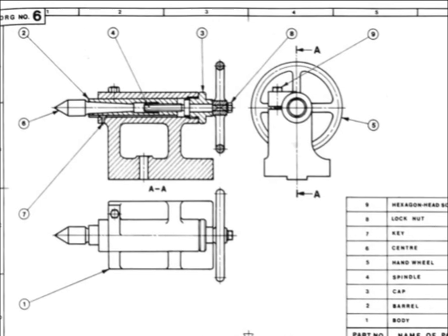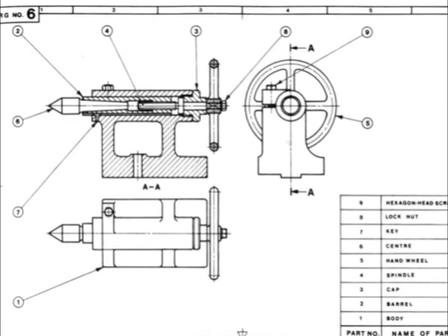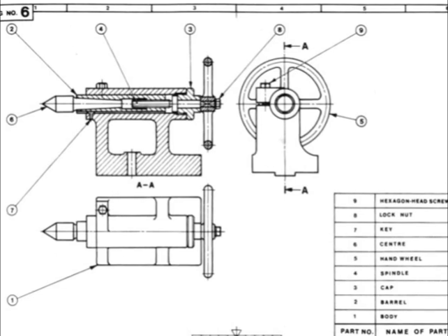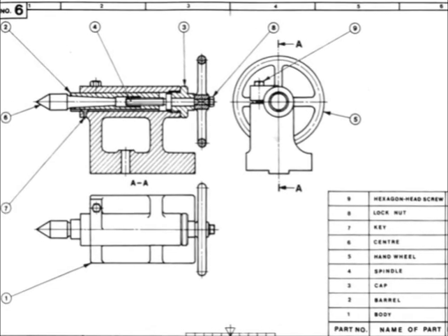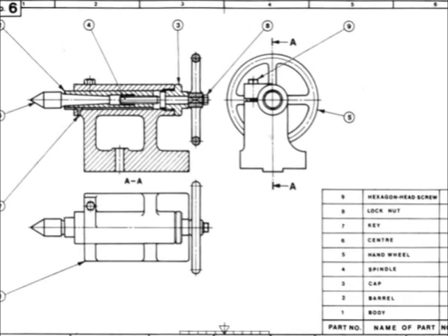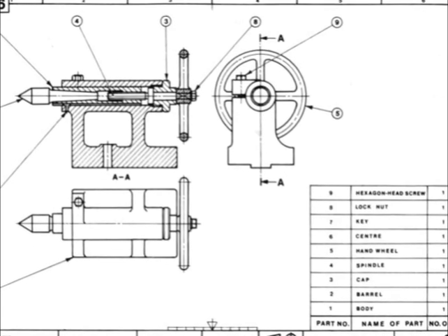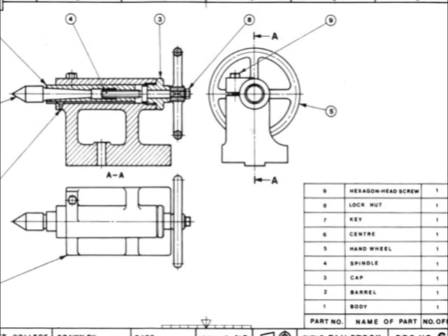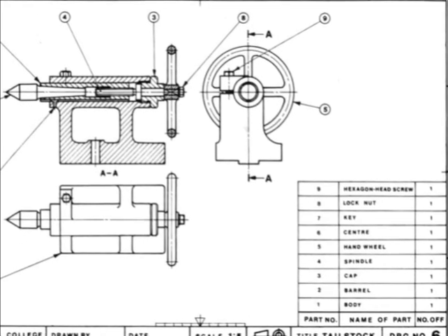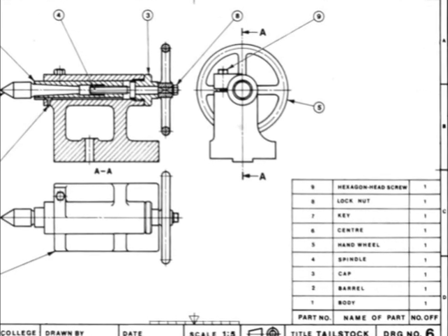Assembly drawings are used to represent items that consist of more than one component. They show how components fit together, sometimes in three-dimensional or an exploded view, showing the relationship between the components. They may be used to show how to assemble parts of a kit, such as furniture, how to assemble a complex part of a building, or to show the relationship between a number of details.